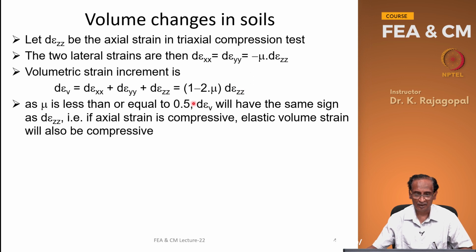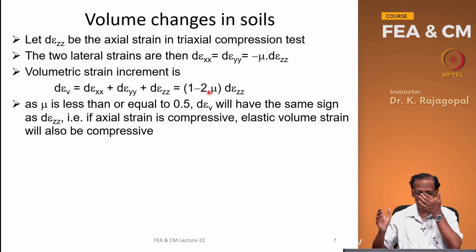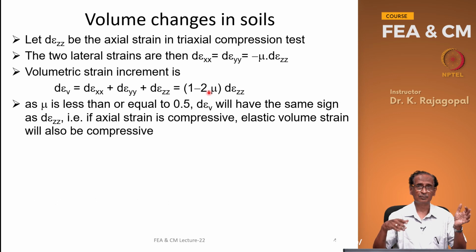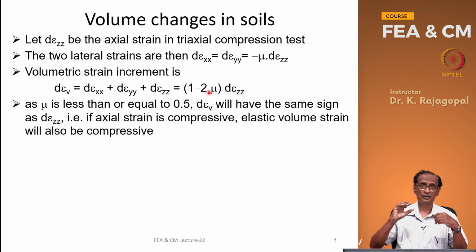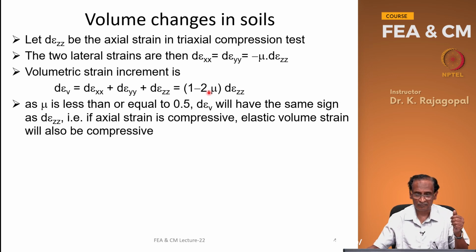And so, our Poisson's ratio is less than 0.5. The theoretical range is from -1 to 0.5, but negative Poisson's ratio is impossible, because we see that if you elongate in one direction, in the other direction there is compression, or if you compress in one direction, there is elongation in the other direction.